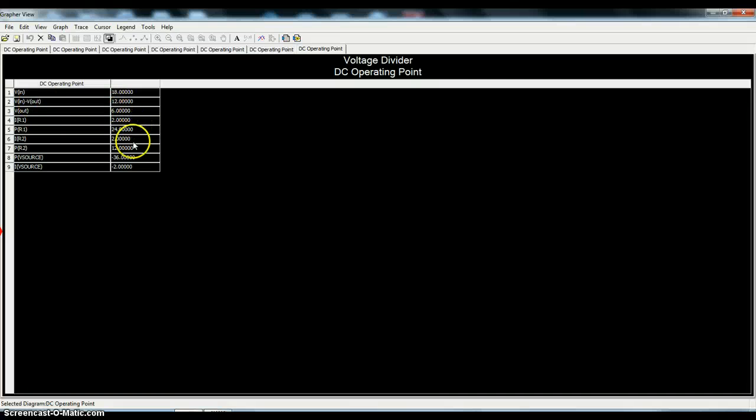Now, for the power values in the circuit, we have P of R1. Now, I was 2, so I squared times R is 4 times 6, which is 24 watts. Now, P of R2 would be I squared times that resistance, so that's 4 times 3, which is 12, or you could take V times I. That certainly will give you the same result.